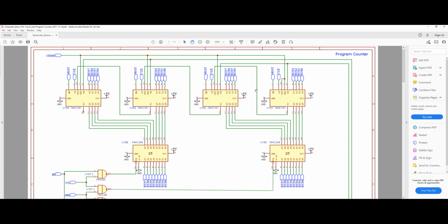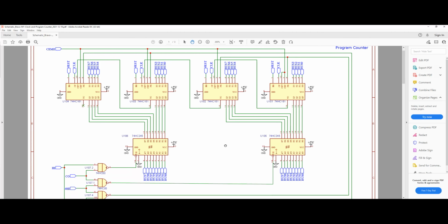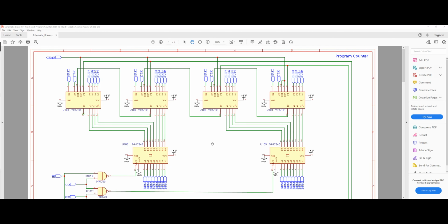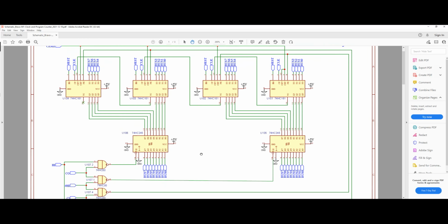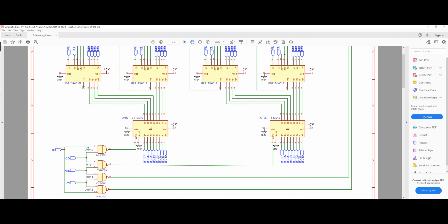So once that operation is completed, then we're going to activate the circuit on the left-hand side, these 2 chips here, and then we're going to repeat the same process. As you can see here, we probably need a control mechanism to be able to enable the low byte side or high byte side at each point of time. And that has been implemented using an extra signal, which we call HI, or high signal here.